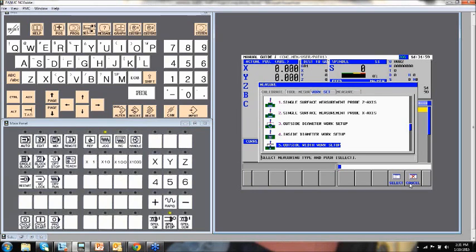And again, over the last 4, I've also talked about the flexibility of Manual Guide i, because with this, it sort of gives you a choice of where you want to go. Because, like I said before, typically when I measure something, the way I was trained was, the top of the part was Z0, and the middle of the part, wherever that is, whether the part was symmetrical or whatever, the middle of the part was always X and Y0.